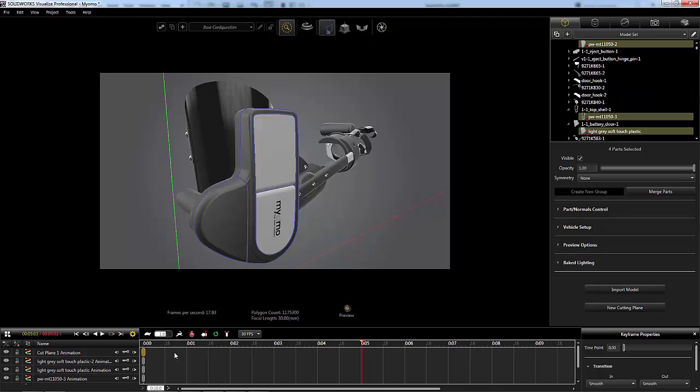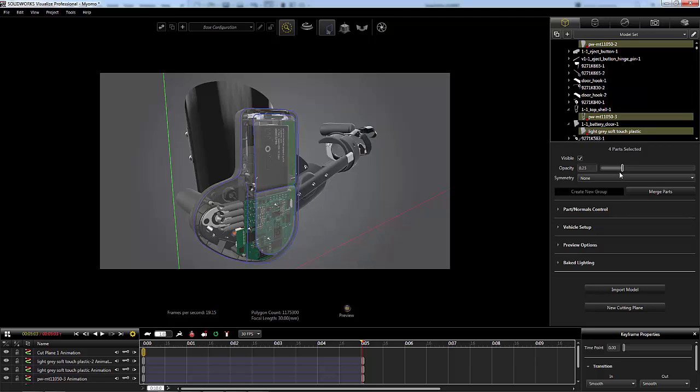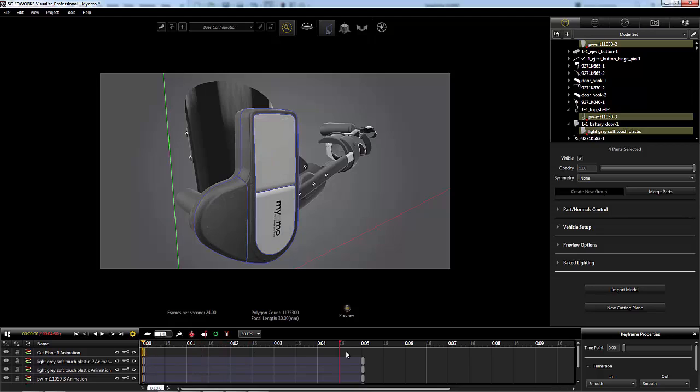So once again, I captured a keyframe of this part in its initial state, created a timeline for my movie, and now I have this opacity slider bar where I can dictate just how transparent I want those different currently existing appearances to be. So let's go somewhere right in there, and once again, look at our timeline movie here. Oops, let's drag that red back. You can see as we start to transition through time, we get some more transparency on those different objects we selected.